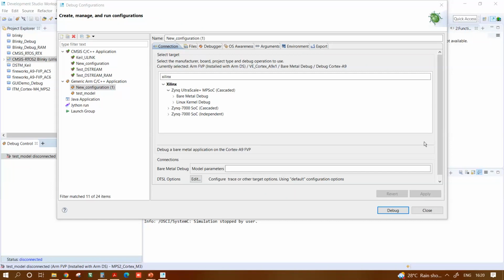Yeah, for adding peripherals in simulation, as I told Vinay, what I demonstrated was an FVP, a Fixed Virtual Platform, which is a simulation model developed for the MPS2 board. So you could see all those LEDs display and all. But if you want to add peripherals to the simulation models, then you have to use the ARM simulation models or ARM Fast Models. Here you can develop your own simulation models. TFT display simulation, I don't have any sample project for that.